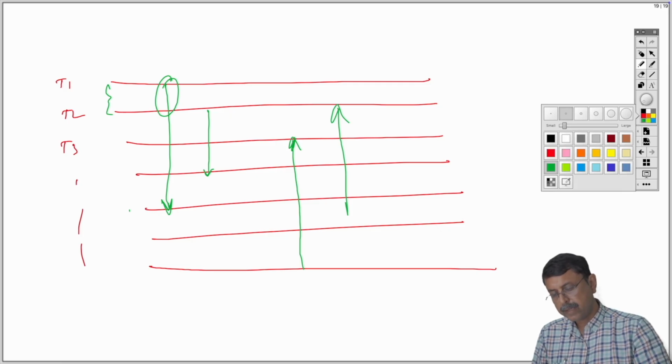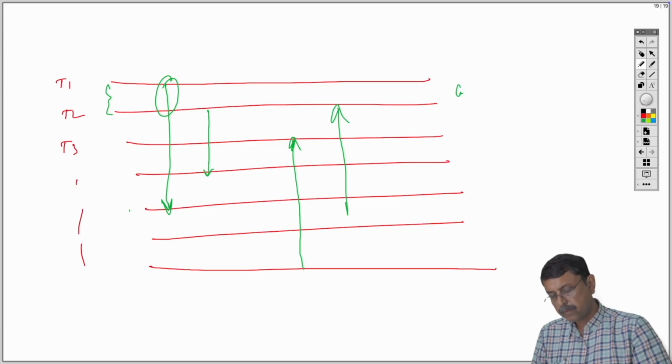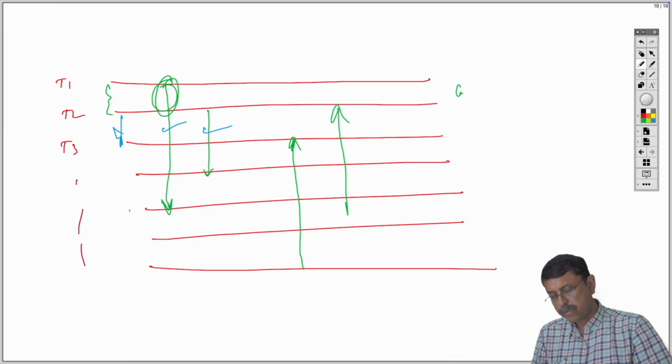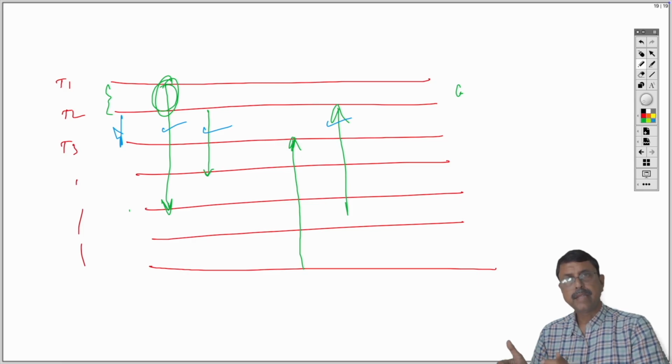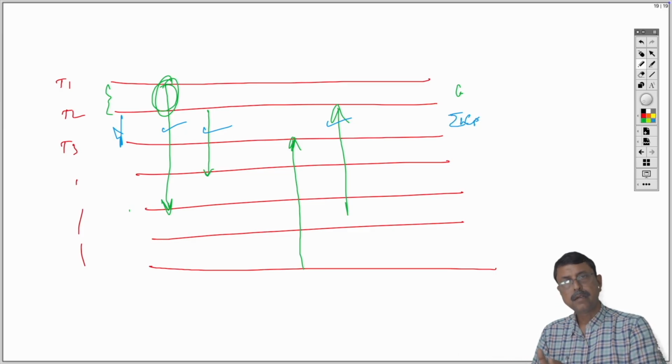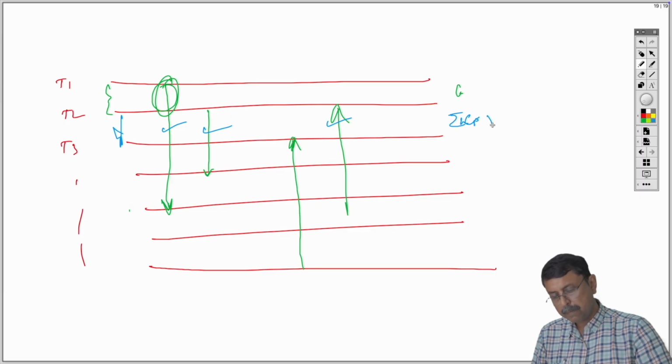So you can say that only MCP of only this one will be active between these two temperatures. Whereas for the second gap, we have 1, 2, 3. Three such streams, they contribute into that temperature gap. So MCPs of all of them should be counted together, multiplied with the temperature difference.